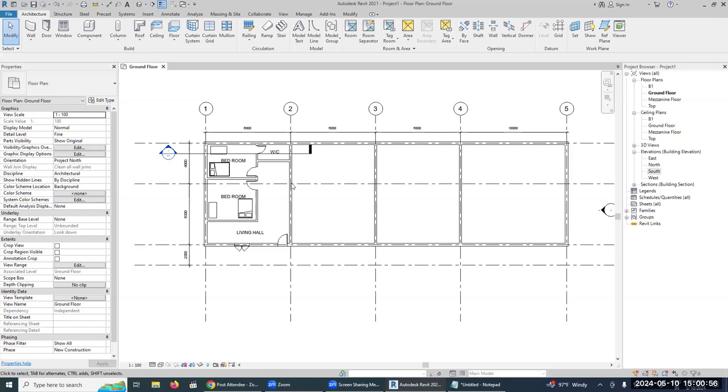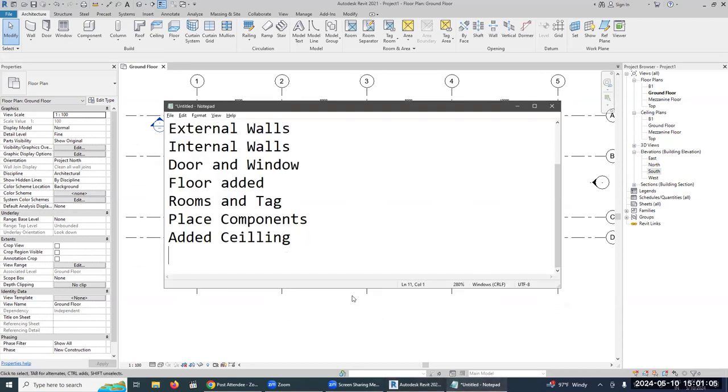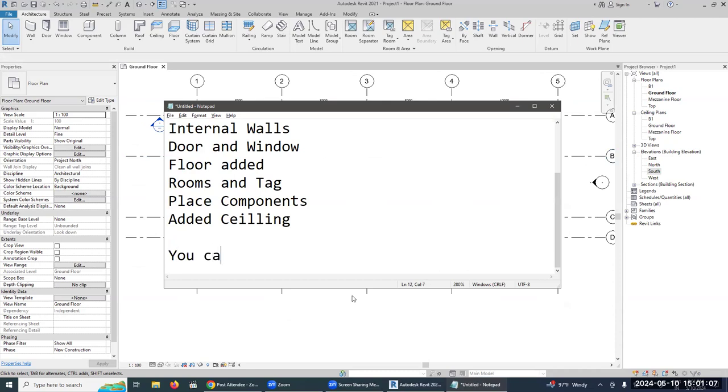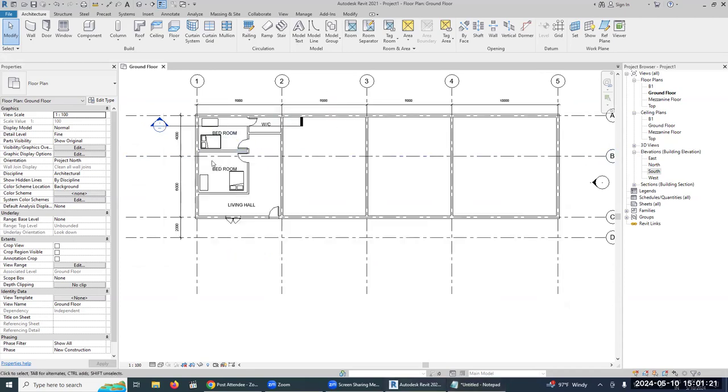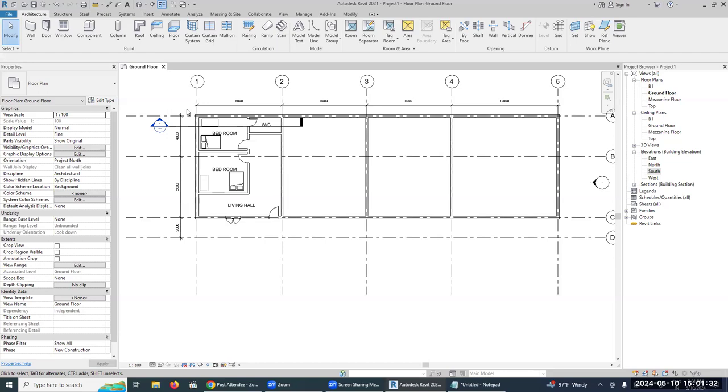Look at this one very carefully, how I'm going to do it. See here. Remember, you cannot mirror rooms. I'm clearly telling you. You cannot mirror rooms. So in your selection, if a room is included, you have to remove it. Okay. Now how am I going to select it? I place my cursor here and now move around.